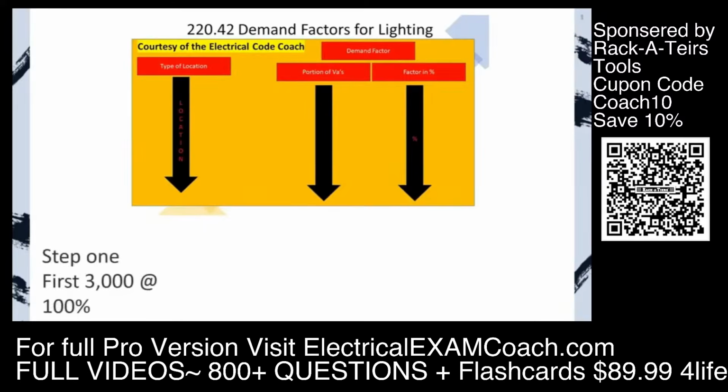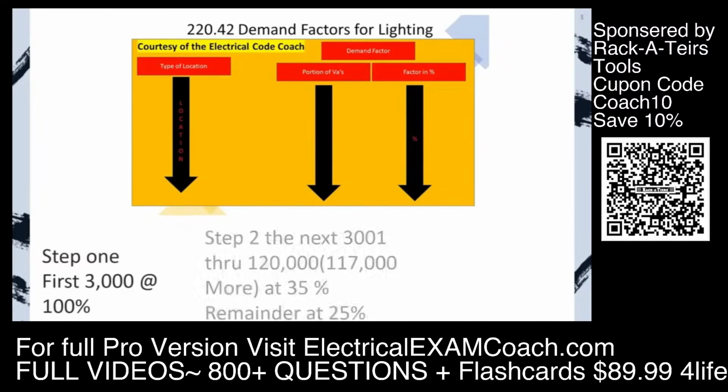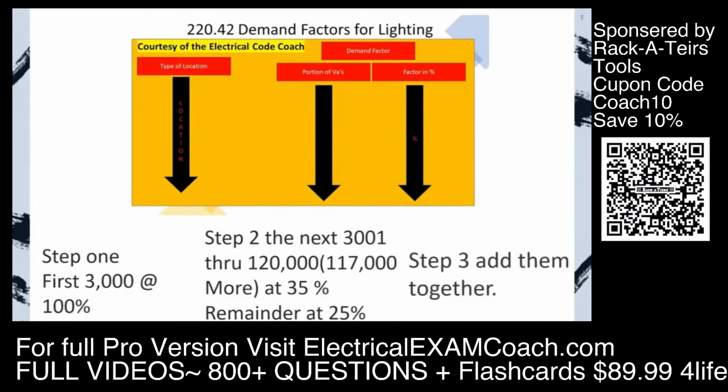Step 1, we're going to take the first 3,000 VAs at 100%. Step 2, we're going to take in between 3,001 through 120,000, which is technically just another 117,000 more. And that's how I'm going to refer to it for the rest of the program. We're going to take that percentage at 35%, and then we're going to take anything above and beyond that at 25%. Then step 3, we add them back together. We take the original 3,000 that we set to the side. Then we're going to take that new reduced load, add those two together, and that's going to give us our total load.